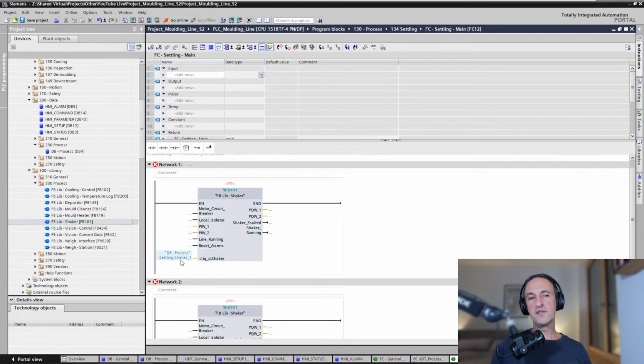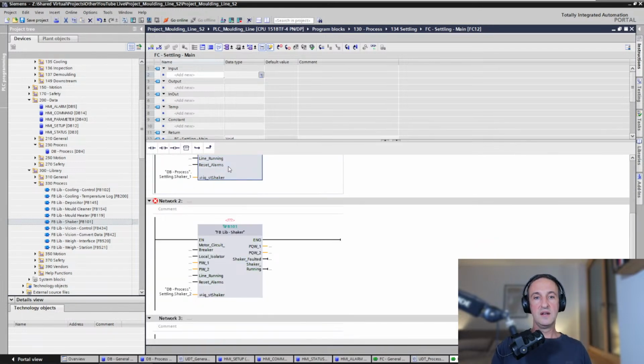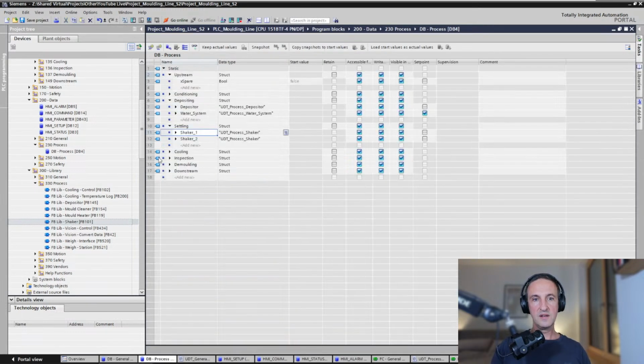So see, this is the reason that I've segmented them like this. The problem is if you would have done it as a whole module, then you have to put the UDT of the whole module on the single shaker block, and then how to decide if you're using data for shaker 1 or for shaker 2. So segmentation per unit, and then each module you just fill with the correct units for that module, just like here. So it's a little bit different than with the general modules.